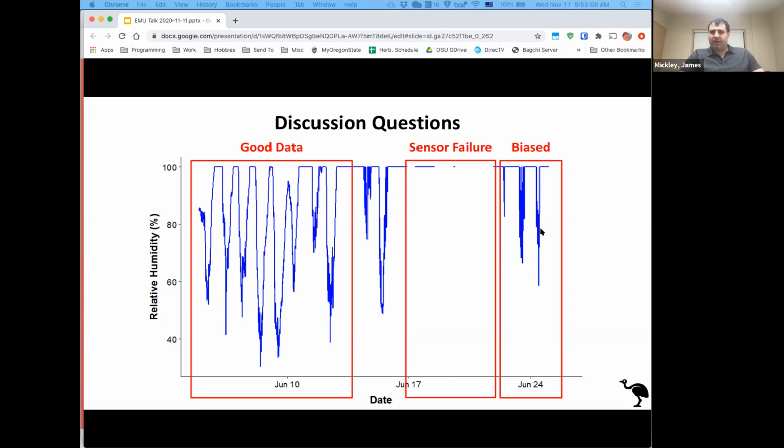And the other issue is that humidity sensors, and I believe all humidity sensors, at least digital ones, have a tendency to get saturated. So if you take a humidity sensor up to 100% humidity and you keep it there for a while, then it will read high for some period of time. And we don't know what that period of time is. It might depend on how long they've been saturated at 100%, and it might vary between sensors, even of the same brand. So it's quite complicated because your accuracy and precision can vary over time and across the range of a